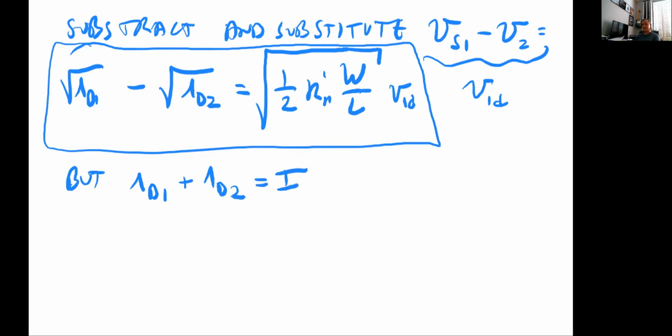So really the way that this differential pair is operating is that the sum of the currents of the drain of both transistors is always constant. And the way that it's working is by the differential input creating unbalance in these currents and developing a differential output. So that is the effect of that differential amplification. But this is a constant.